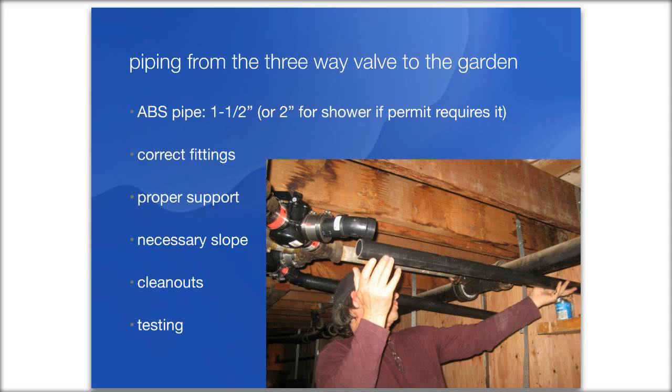Okay. So the first question is about where to divert the water. This person has their shower drain first, and the second sink, let me just read it. It says, if my plumbing is structured with shower drain first, then sink second, where the vent is, then the drainage goes to meet the toilet. If I only want the shower for Greywater, do I need to set up a new vent connection upstream, since the three-way valve will be in between the shower and the sink? Oh, they didn't plumb it with a separate vent for the shower, is what I'm gathering.